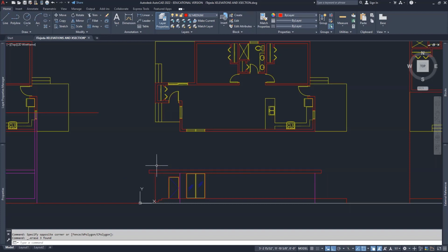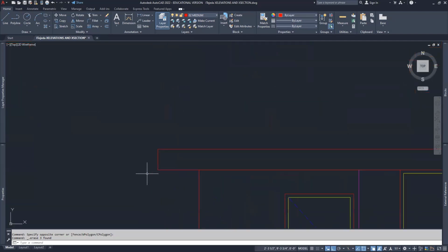Obviously, if I go over 12 inches and come up 12 inches, that's a 45-degree slope, and that might be a little too much. I like to keep my roof shallow, so I'll go with a 12 run and a 3-inch rise. So that's a 3 in 12 slope. Let me show you how I'm going to put that in.